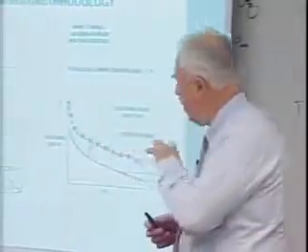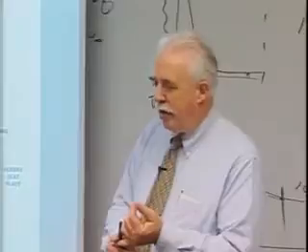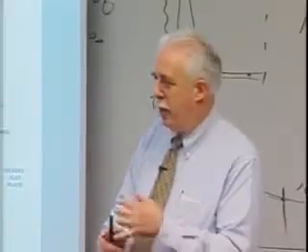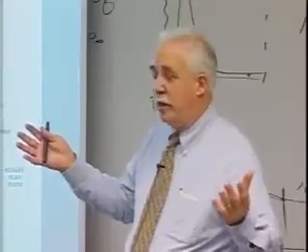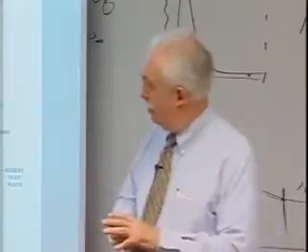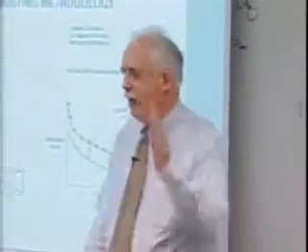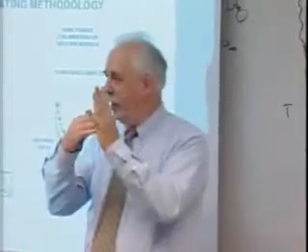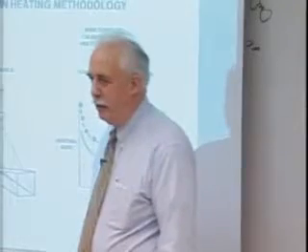All right. I mentioned 3 levels of aerothermodynamic methodology. One is to correlate in the wind tunnel and relate everything to reference heating or stagnation point heating, which is what we did on the capsules, which are good blunt vehicles. The real technology challenge on the shuttle was the geometry. It was a lot more complicated than just a shock and a stagnation point and flow around a blunt vehicle, okay? You name it, you've got it in terms of flow on this thing.